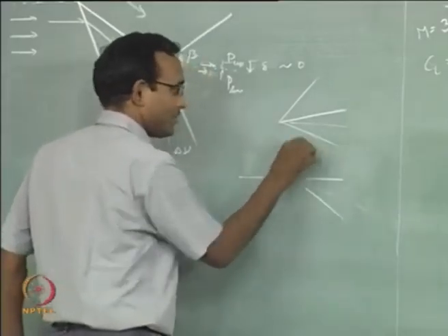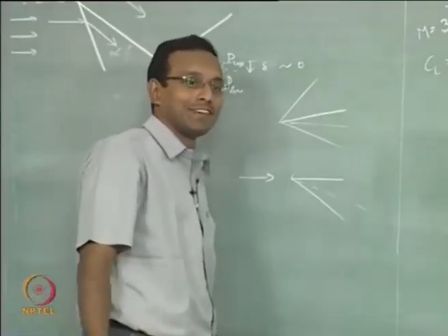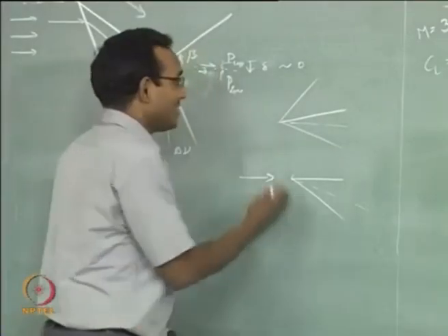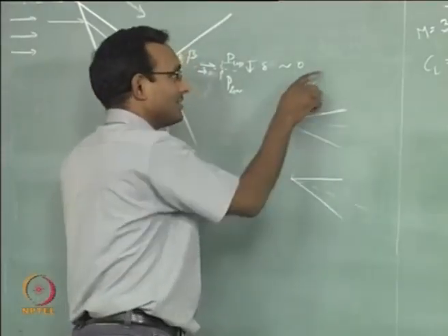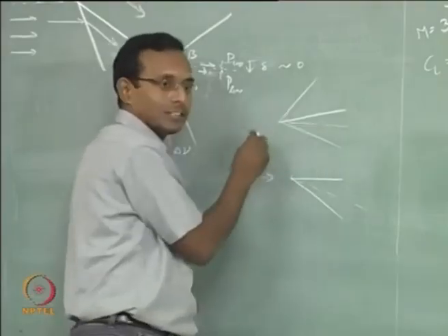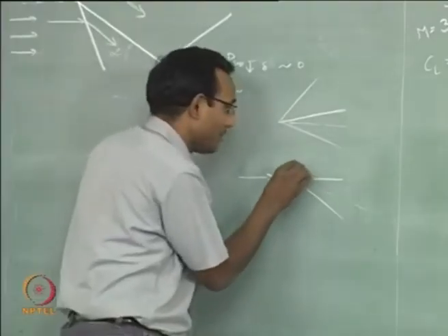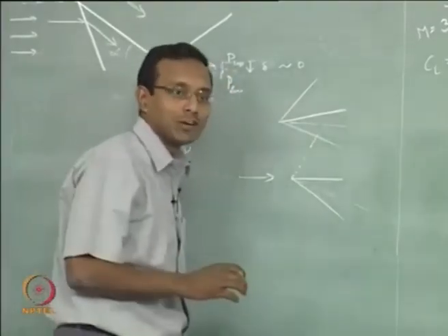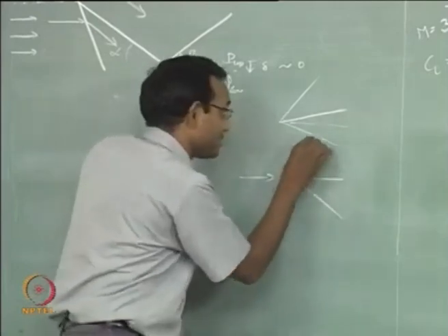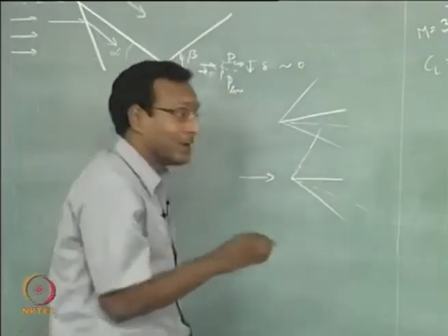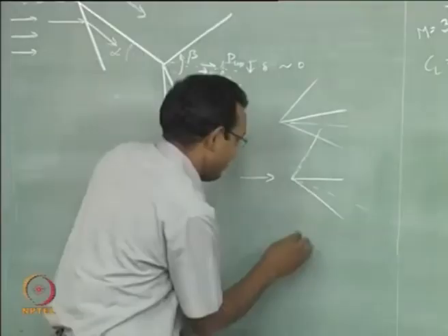What wave will be there on the top? No wave? I do not like that. There is always a wave and we call it the Mach wave. If I think about the continuous change of angle of attack, what is really happening is this oblique shock is going to become weaker and weaker and weaker. Eventually the beta will become equal to mu. That is where it has the weakest oblique shock, the Mach wave. If I go any lower, that Mach wave does not change, it stays there, but there are more Mach waves downstream which eventually form your expansion fan.